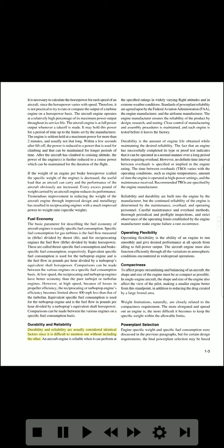Durability and reliability. Durability and reliability are usually considered identical factors, since it is difficult to mention one without including the other. An aircraft engine is reliable when it can perform at the specified ratings in widely varying flight attitudes, and in extreme weather conditions. Standards of powerplant reliability are agreed upon by the Federal Aviation Administration, FAA, the engine manufacturer, and the airframe manufacturer. The engine manufacturer ensures the reliability of the product by design, research, and testing. Close control of manufacturing and assembly procedures is maintained, and each engine is tested before it leaves the factory.